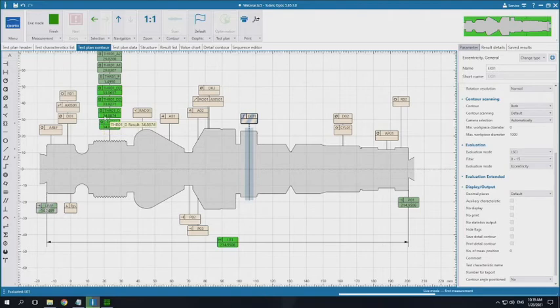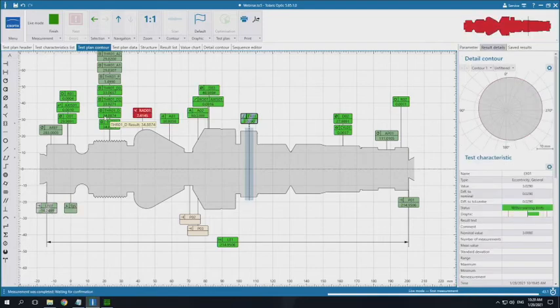But usually you need the actual profile of the cam. So different types of cams have different profiles and you need to upload that into the machine beforehand. So eccentricity, yes. Lift, yes. And the angle, yes. Those are usually the main things. And then a profile, there is a separate license for the machine that you need to buy just to do cam profiles. We've got it on this one, but I don't think it's worth going into that right now.